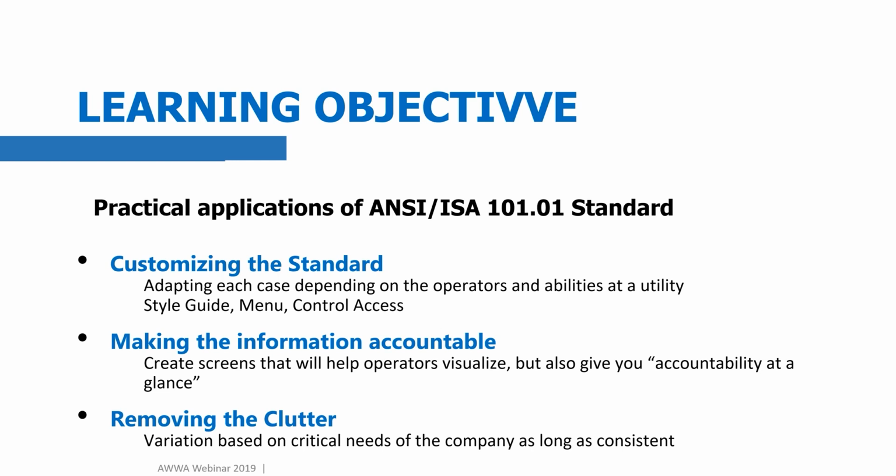As Haley mentioned, using grayscale and color to be able to enunciate information. So you'll see in some of these examples that are following that grayscale can be used to indicate whether an item is active or in standby or not available. But color, especially using red or yellow to indicate alarm and warning information, draws your attention much quicker to the item that needs action than just giving you green or red telling you that it's just on or off.